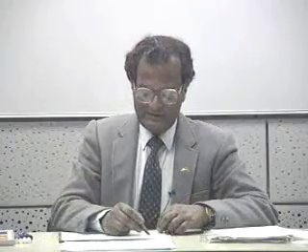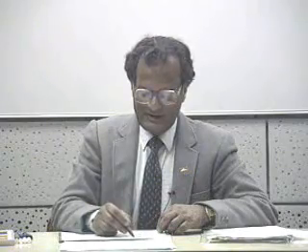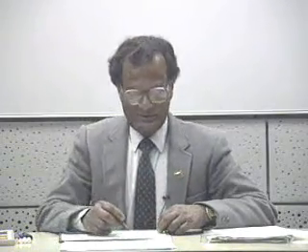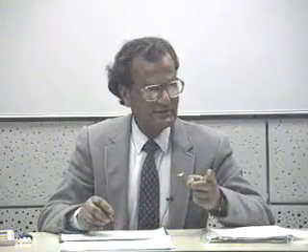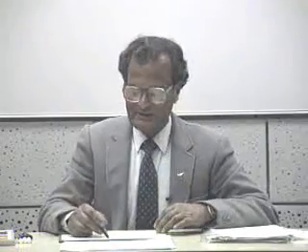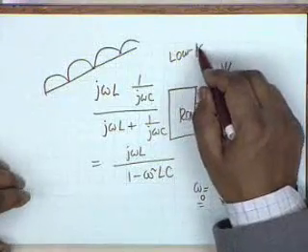Or in the case of a power supply, you have two diodes, a transformer and a rectifier circuit, which produces, the full wave rectifier produces something like this. What you wish to do is to retain the DC and reject all the alternating components, and therefore you require what is known as a low pass filter.